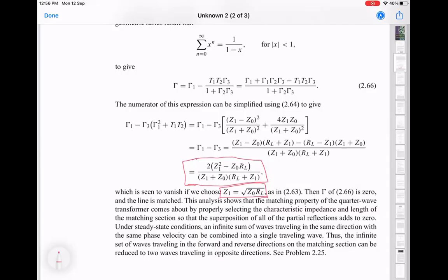Any other questions? You said that when you have two transmission lines, this is Z0 and Z1. Yeah. So it's equivalent to having a Z1 load right at the junction, if that Z1 line is infinitely long. Then it's the same thing as having that. Yes.